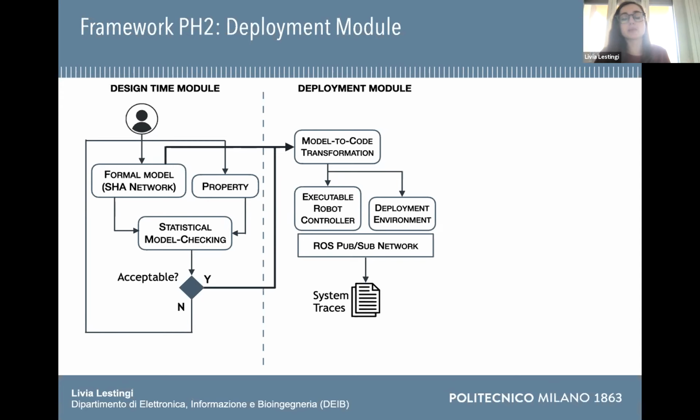As for the agents themselves, and the deployment environment, so far I have been working with a fully virtual deployment environment, with simulated humans and simulated robots in a 3D simulator environment. Right now, I'm working on a hybrid deployment environment. So I have a physical robotic device which interacts with virtual human agents in the simulated scene. In both cases, the controller and the agents interact with each other over a middleware layer, which is based on ROS. So it is a network of ROS publisher and subscriber nodes.